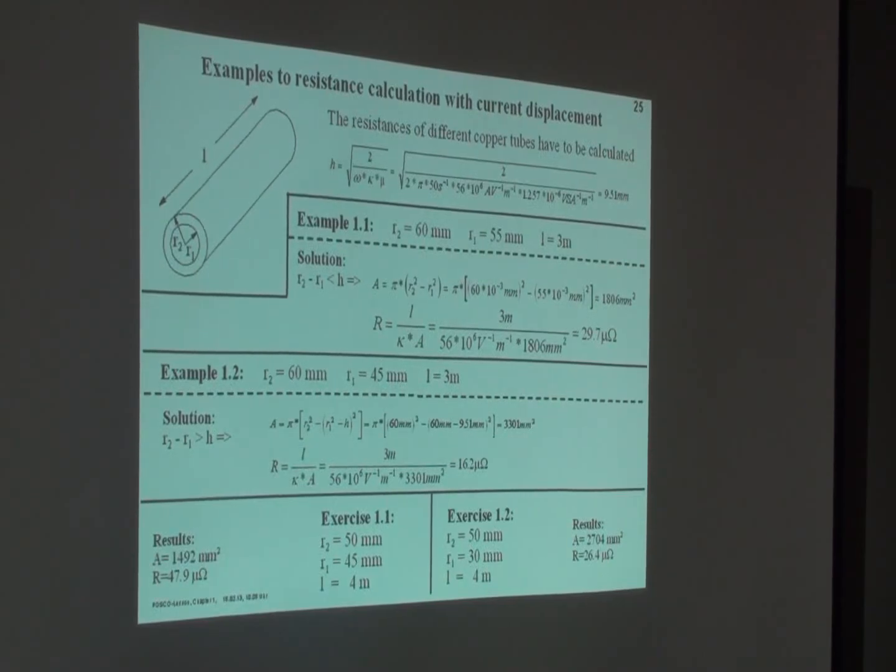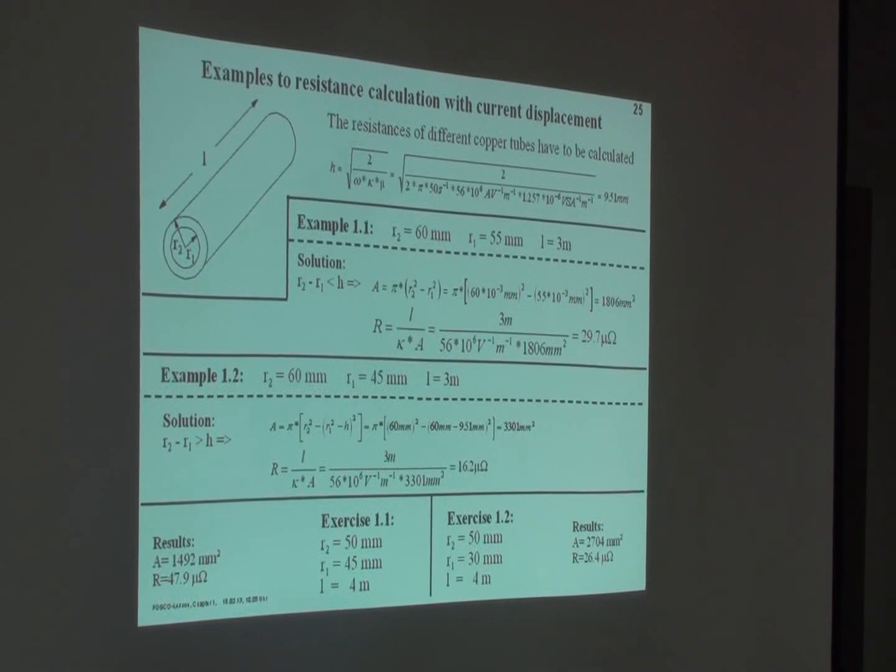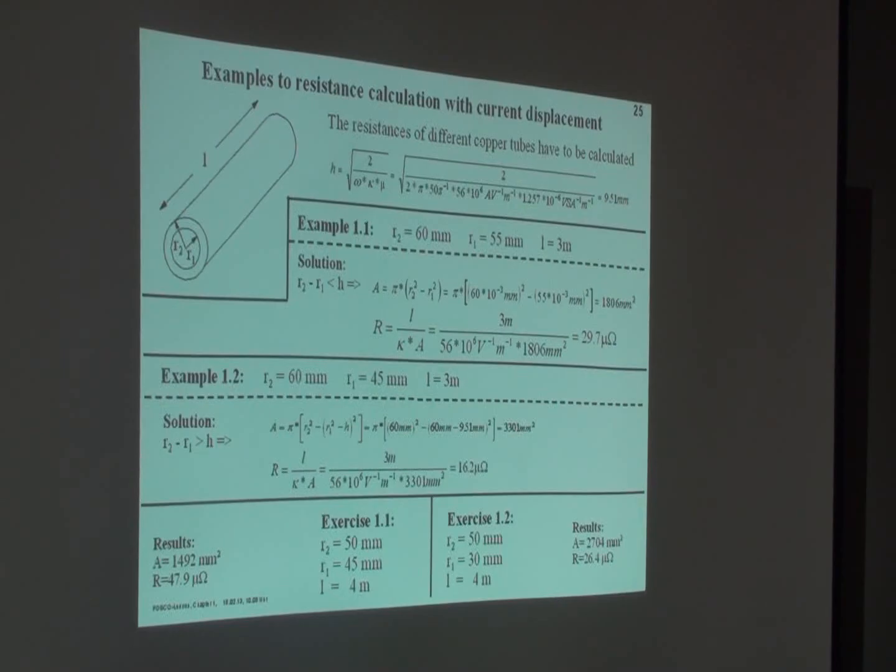I made a measurement. I had a problem, and I made a measurement with a field strength, magnetic field strength. It was copper, like this, at 50 hertz. I made a measurement with a Hall element, and I measured the field strength. If you have such a copper bar, the field strength is all the same between here, and it decreases here.